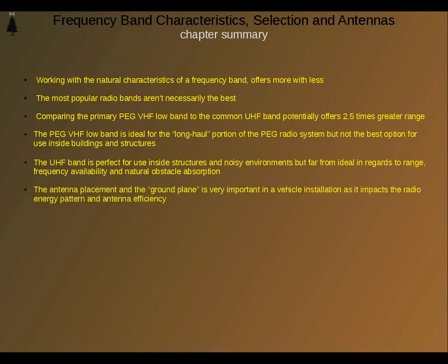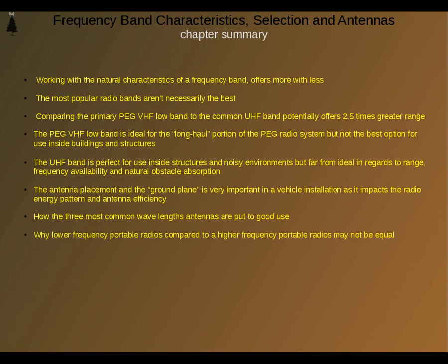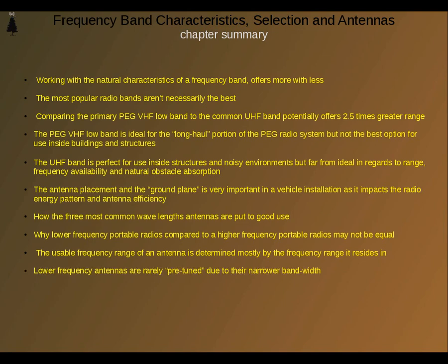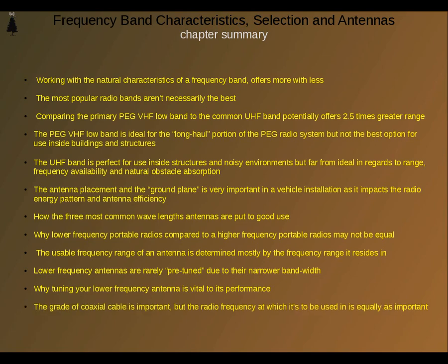The antenna placement and the ground plane is very important in a vehicle installation as it impacts the radio energy pattern and the antenna efficiency. How the 3 most common wavelength antennas are put to good use. Why lower frequency portable radios compared to higher frequency portable radios may not be equal. The usable frequency range of an antenna is determined mostly by the frequency range it resides in. Lower frequency antennas are rarely pre-tuned due to their narrower bandwidth. Why tuning your lower frequency antenna is vital to its performance. The grade of coaxial cable is important, but the radio frequency at which it's to be used in is equally as important.